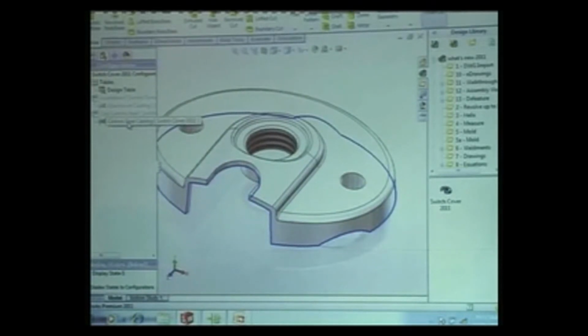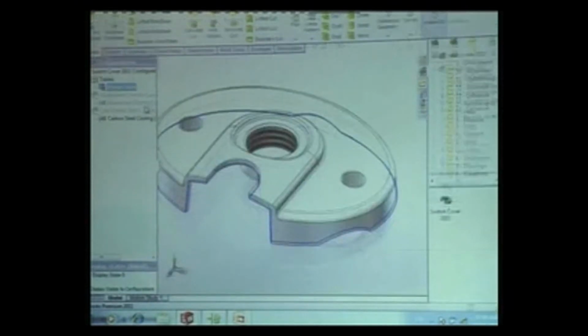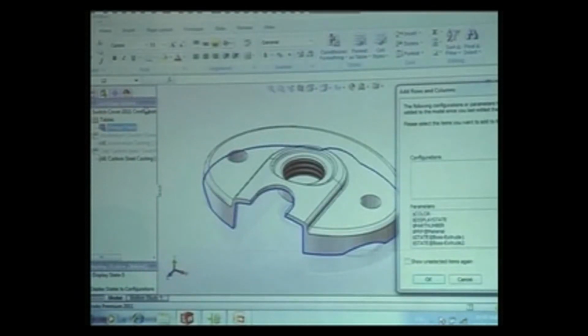This is suited for this kind of casting product, which has a lot of configurations based on multiple materials. But I can configure the materials separately or outside this window, right? It is possible, but you cannot incorporate even the shrinkage value configuration. Yes, that is right. That's what we have enhanced in the 2011 version, wherein it is now possible to incorporate all those shrinkage values and configure them inside the design table. Not only shrinkage values, it also comes with global variables as well as thread callouts for cosmetic threads.